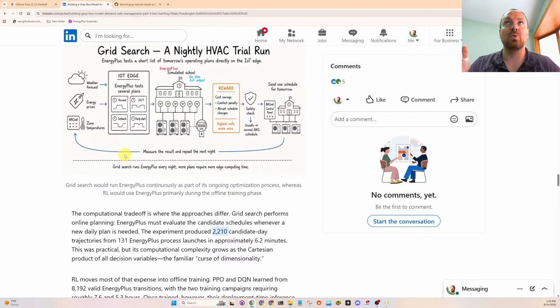In that scenario, you'd want it running every 5 or 10 minutes, with a machine learning process happening in between, which would need really expensive hardware. But I think just running this once a day at midnight, rolling the dice, setting the building automation schedules and setpoints, and then waiting until the next day to do it all over again, works here.